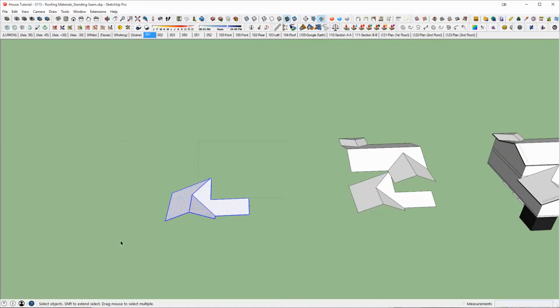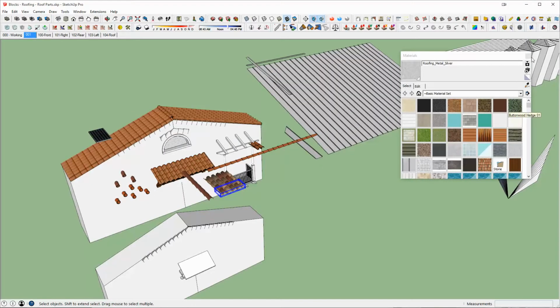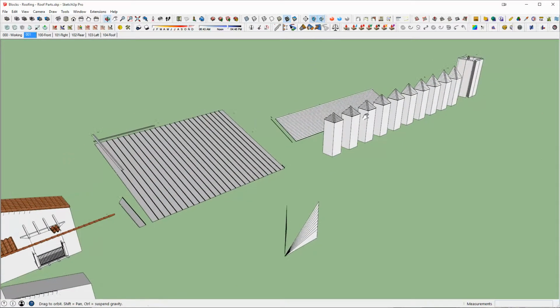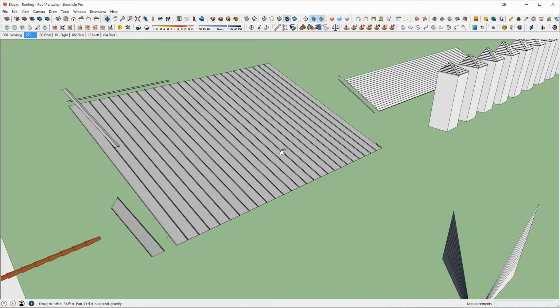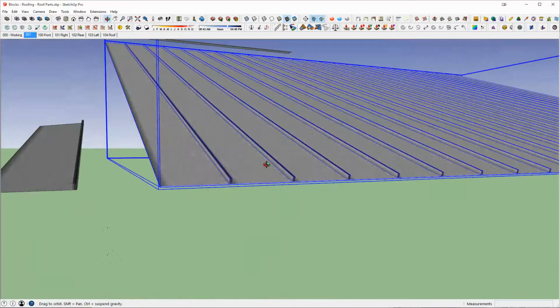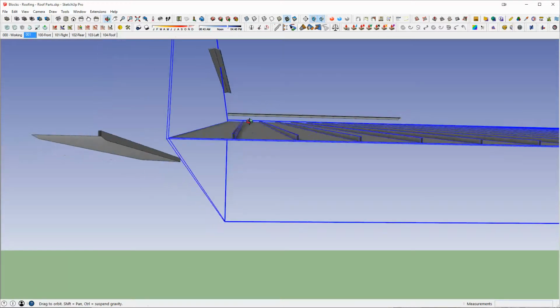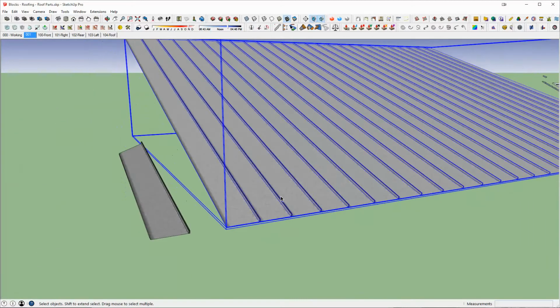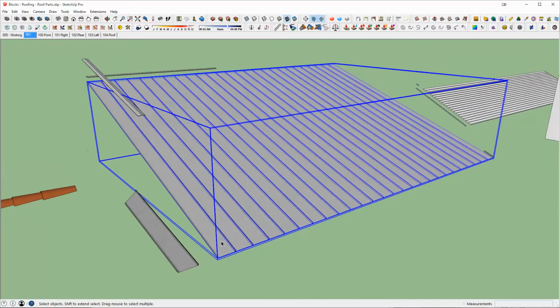100 feet, and I'm going to use my flattening tool, which just makes it flat, which makes it really easy to create my cutting boxes I need for the roof. And going back to my roof, my roof parts block that's on the server, I'm going to use this plate here, which is just my standing seam, the three-dimensional version of it that shows the seams going up and just adds a lot of detail versus just painting it.